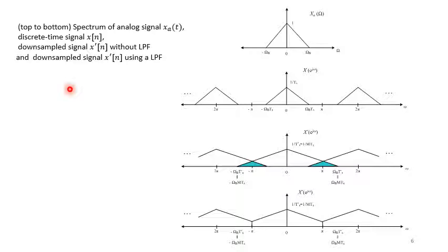And once we replace omega s, we have this relationship between the continuous time signal frequency and the discrete time signal frequency. So simply it is the scaled version, right? And the scaling is the sampling period. So if we multiply the two, we get the discrete time signal frequency, and that's basically omega s into ts. That's the result into 2 pi.